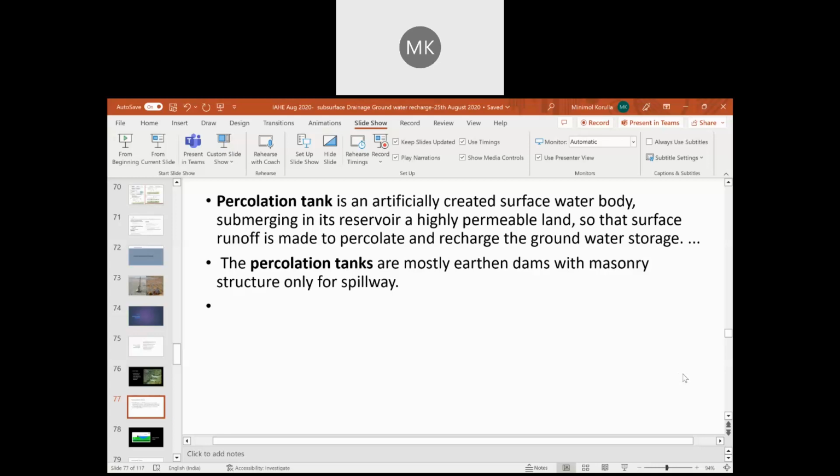Okay, we are inserting horizontal pipes randomly. We may be trying to insert it in an impermeable rock, which will be troubling the contractor. But if we are doing a permeability analysis, we will understand where the pervious layer is, where the impervious layer is, whether an inclined pipe will be useful, and where I have to insert a drainage gallery.